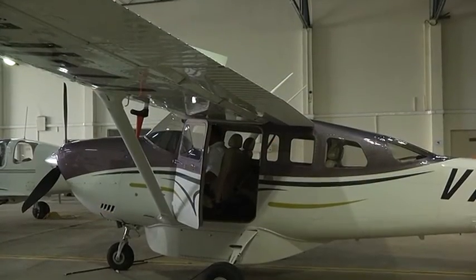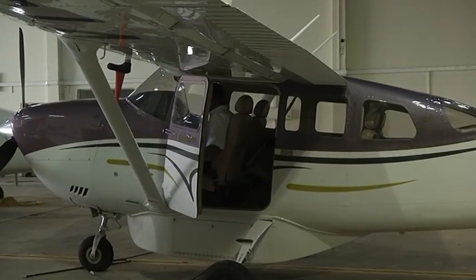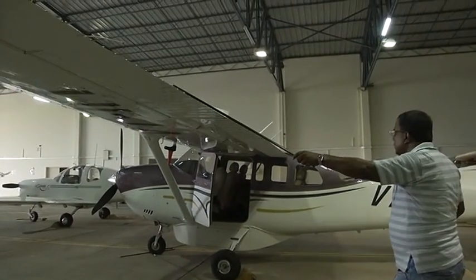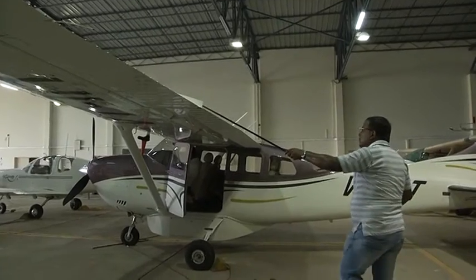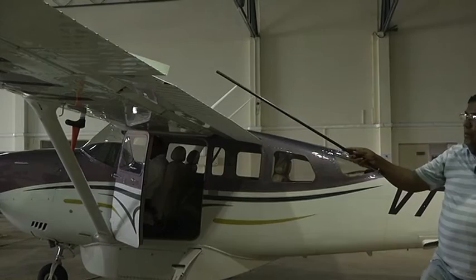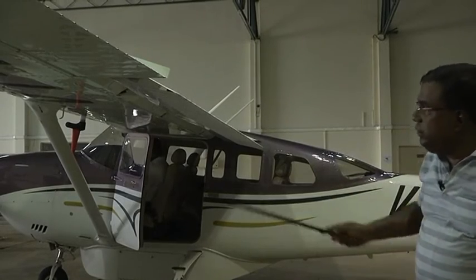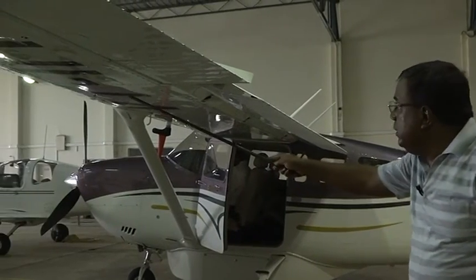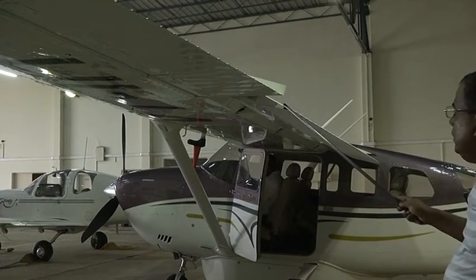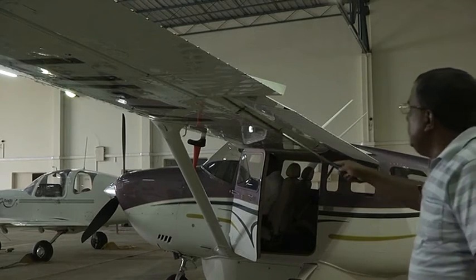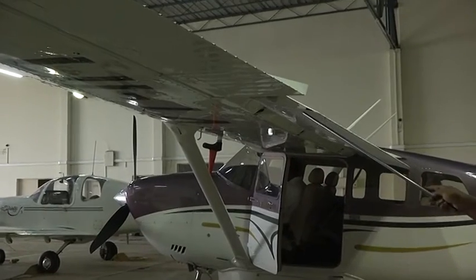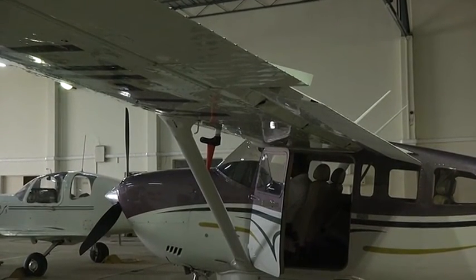Now, I am drawing your attention to a Cessna 206 airplane. You could see that these are the aileron, right? And this is the flap. Okay? See, we are now putting the flap down. What is happening? Please look here. This aerofoil now locally is having a camber. Could you see this? By putting the flap down, it is adding camber to this section. And we know cambered aerofoil will produce more lift.